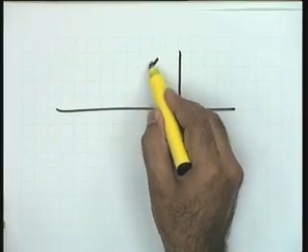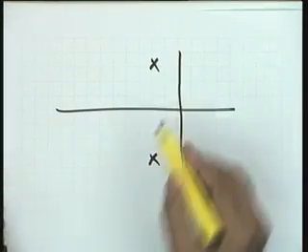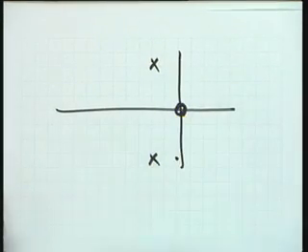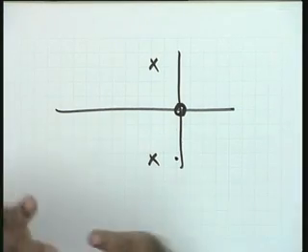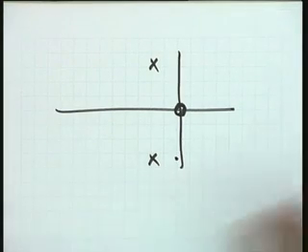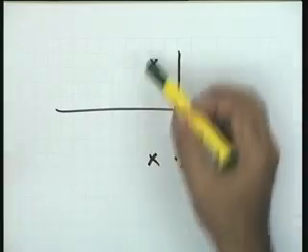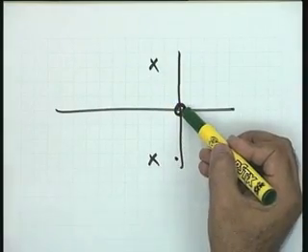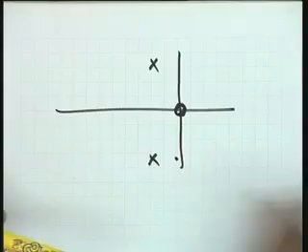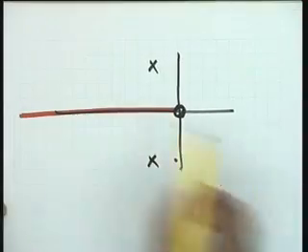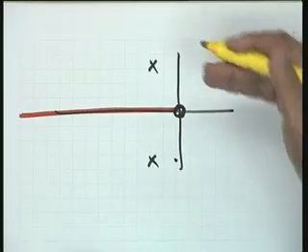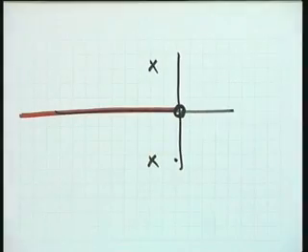Okay? One more, again, to exemplify this rule, let me take this particular sketch. This sketch I have just now taken today itself, right in the beginning. Let us take this situation. Help me please. Corresponding to this situation, what type of root locus do you suggest? In this particular case, there are 2 poles. One will terminate at 0, the other at infinity. The 2 root locus, and this you know is the total root locus branch. So is it not that the 2 branches will come and break away?